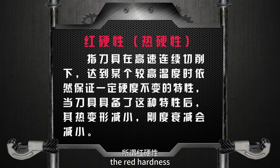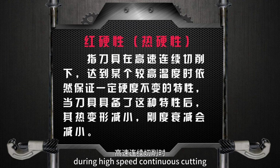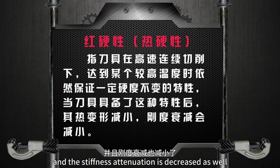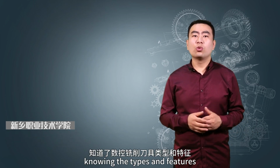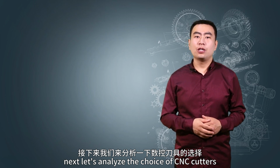The red hardness, also named heat hardness, refers to the characteristic of a tool that can maintain a certain hardness when it reaches a certain high temperature during high-speed continuous cutting. With this characteristic, the cutters have reduced thermal deformation, and the stiffness attenuation is decreased as well, thus meeting the requirements of high-speed, efficient, and high-precision machining of CNC machine tools. Knowing the types and features, we also need to know how to choose the cutters. Next, let's analyze the choice of CNC cutters.